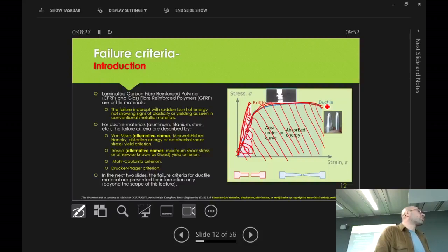Carbon fibers have got high strength and high stiffness. That's what you get out of it. So in the applications, you've got buckling, perfect. Aerostructures, perfect. But in order to compensate for the deficiencies, you add another material. It is possible to have one or two layers of Kevlar to compensate for the lack of energy absorption or ductility in CFRP.